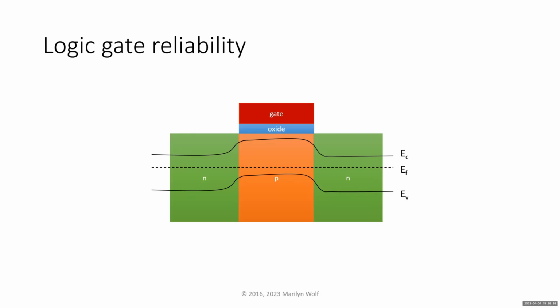On the other hand, those energy barriers are reliability tools, right? The bigger the barrier, the less likely it is that some electron's going to have the energy to jump over it. Okay? So we have a fundamental trade-off between how easy it is to change the value of a gate for performance reasons, and how easy it is for unwanted effects to inadvertently change the gate.